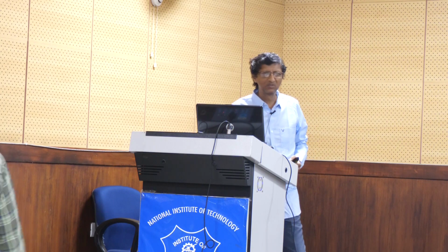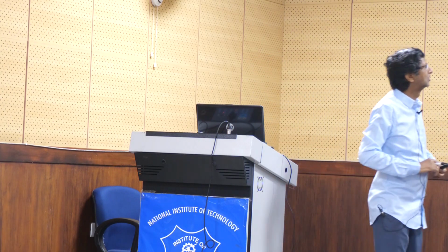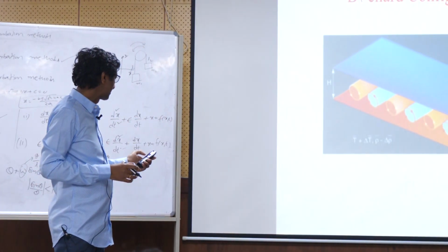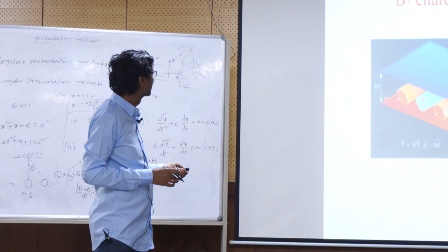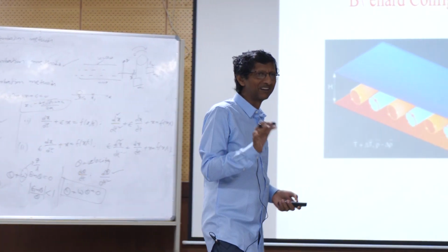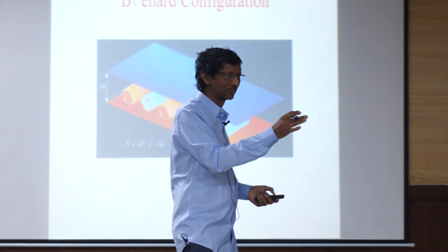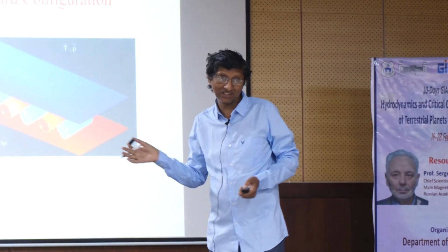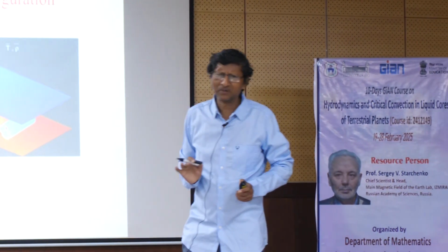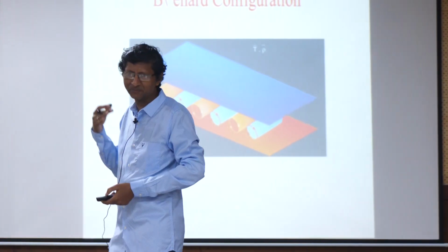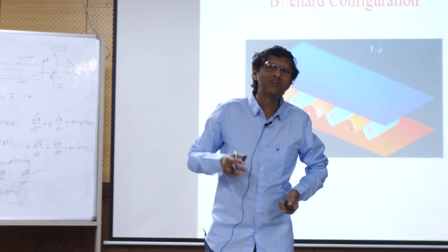This is a classical example: Rayleigh-Bénard convection, to understand pattern formation. How many people know the relevant model? Most of you know that model: take the fluid between two horizontal fixed plates, supply the temperature from below, and observe for what temperature gradient you get motion in the system.